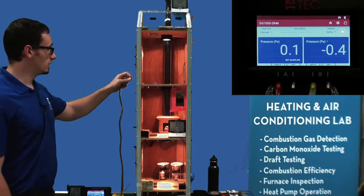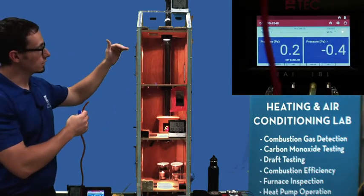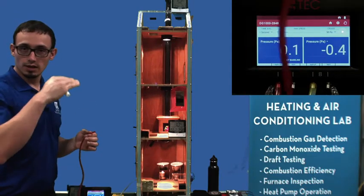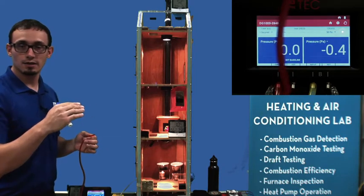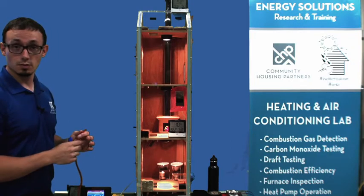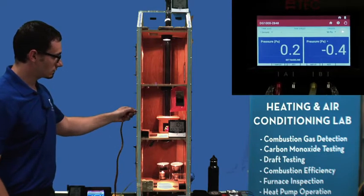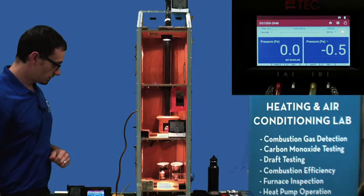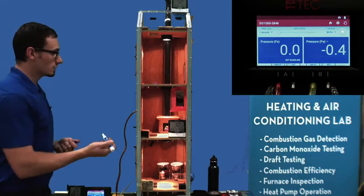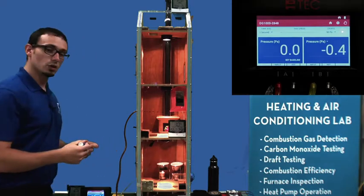Positive 0.2. So as I'm moving away from that leakage location, I'm moving towards what's called my neutral pressure plane. Eventually I'm going to hit a pressure that's equal to that of the outside. Again, the greater the distance from that neutral pressure plane, the more pronounced the pressure is going to be. So let's keep dropping down here. Okay, I think I'm near the neutral pressure plane. I just hit 0 on channel A. I'm going to draw a line here. That's going to represent my neutral pressure plane.